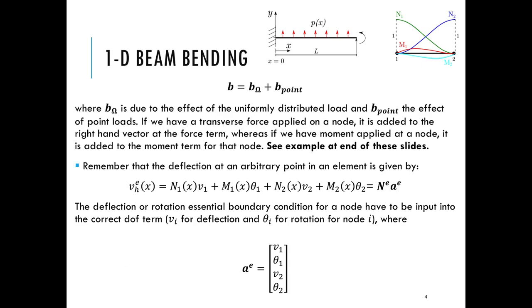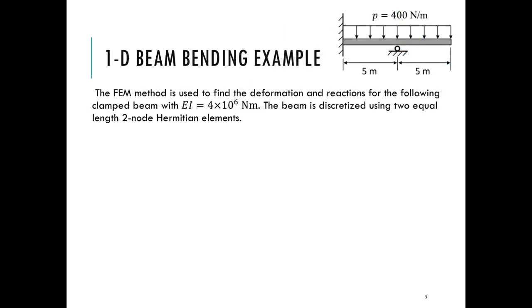So now let's use this whole methodology that we had developed to jump to an actual beam bending example. So we are going to consider this particular problem shown right here, where the left-hand side of the beam is fully fixed, and then right in the midpoint of the beam we have a fixed, no, what is this? Sorry, a roller support, which of course prevents any deflection right here. And then there's a distributed load acting downwards, and its dimensions are also given.